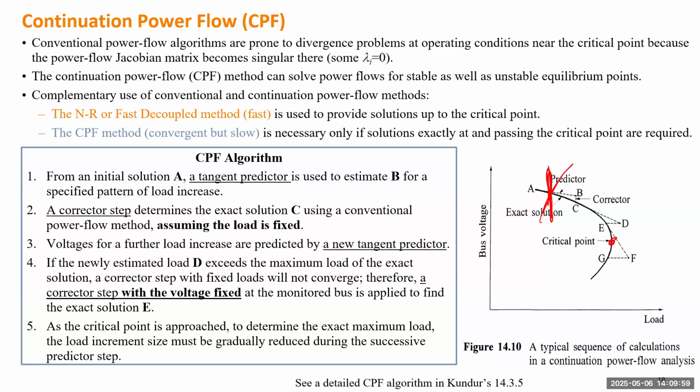It becomes very critical, because some load models cannot guarantee you operate at the equilibrium lower than this critical point. But some engineers still want to see what the bottom part looks like, right? Then you assume this load model, but this load model doesn't exist in the real world. It only gives you a complete PV curve.